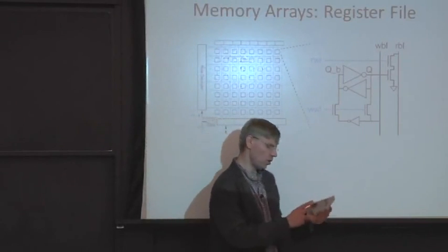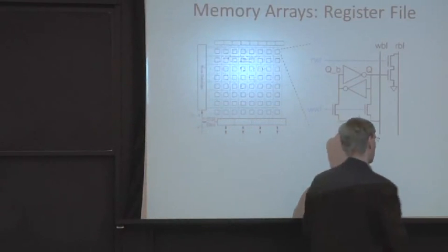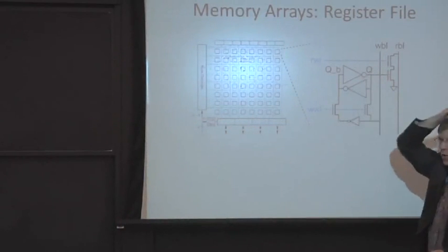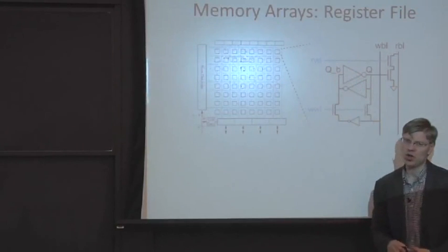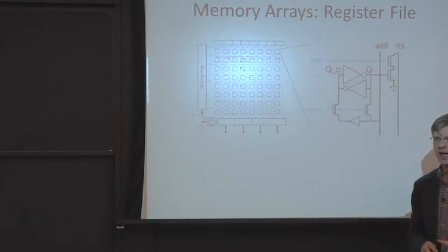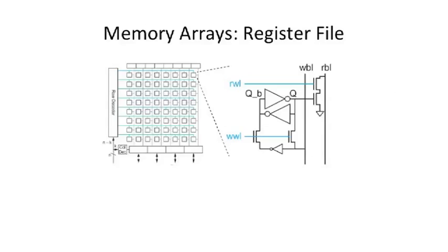And in this register file, I wanted to just walk through what this diagram over here, the circuit level diagram, is. Here we have 2 cross-coupled inverters. And as you'll see, we don't have full complementary logic connecting these two things. But this is a stable storage cell. If you give this power, it'll store data. If we want to do a read, we need to connect the output of this to read bit lines.